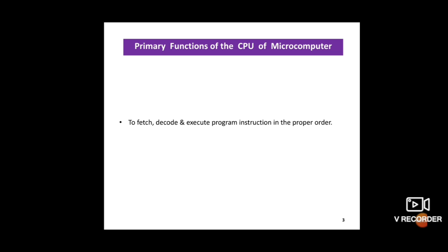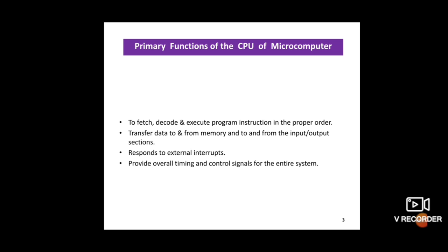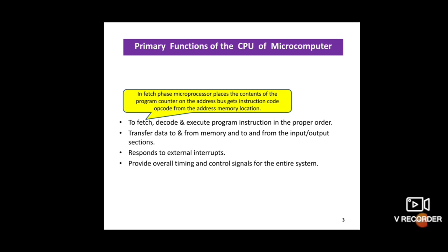What do you mean by fetch? Fetching means, in the fetch phase, the microprocessor places the content of the program counter on the address bus and gets the instruction code, opcode, from the address memory location. This is the function of fetching.